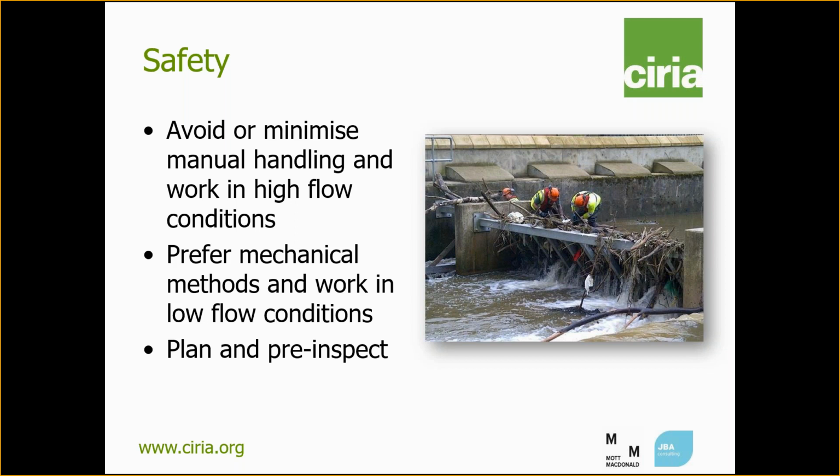It looks like they're standing on the debris, and there's a risk that the debris could move and they could end up falling into the water. It's also important to carry out planning and pre-inspection work to identify hazards and special access requirements, so that inspection and maintenance can be carried out safely and efficiently.